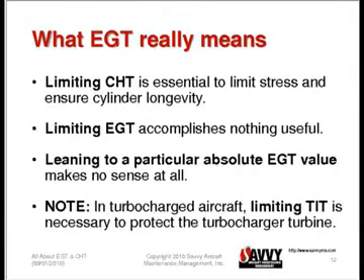Is it jumping up because the engine's under more stress? No, it's under less stress. When we only have one spark plug firing, the combustion event burns much slower and produces less power. That's why we get an RPM drop when we shut off a mag, because the engine is producing less power. But it causes EGT to rise.